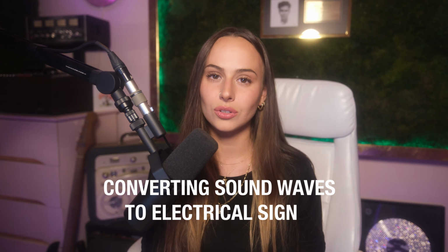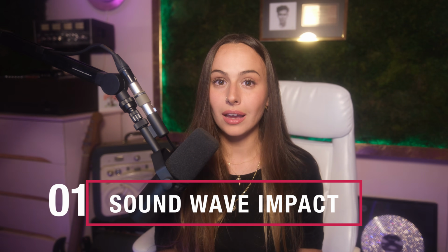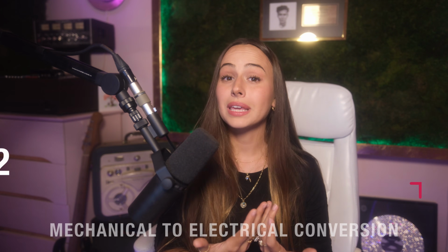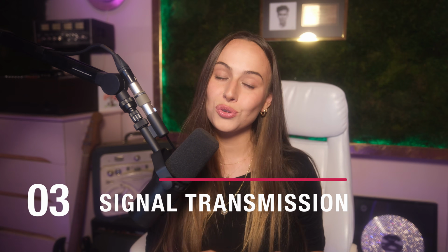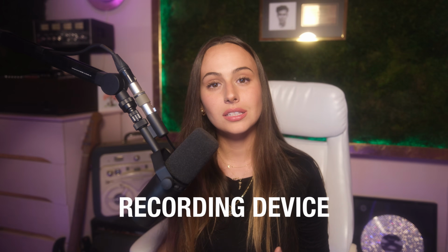So let's go over the process of converting sound waves to electrical signal. The process of converting sound waves into electrical signal in a dynamic microphone can be broken down into the following easy steps. So 1, you have the sound wave impact. The incoming sound waves hit the diaphragm, causing it to vibrate. The mechanical to electrical conversion. The attached voice coil moves within the magnetic field, and electromagnetic induction occurs, generating an electrical current. Signal transmission. The electrical signal, which is an analog of the sound wave, travels through the microphone cable to an amplifier, recording device, or mixing console.